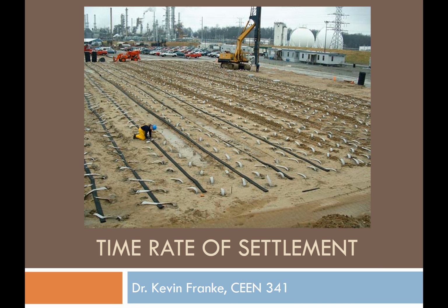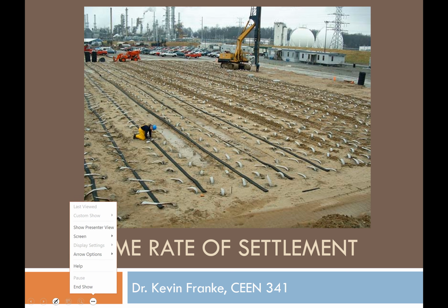And then these black lines that you see here, those are drainage lines that are just running along the site. And once the water leaks out of the drains here, they're going to get into these black drainage paths and travel along the paths and get out that way. So all of these drains, everything, are eventually just going to get completely covered in fill. And so those drains will be completely covered. You won't be able to see them anymore. But that's how we're going to speed up the consolidation of the soil beneath this particular site.